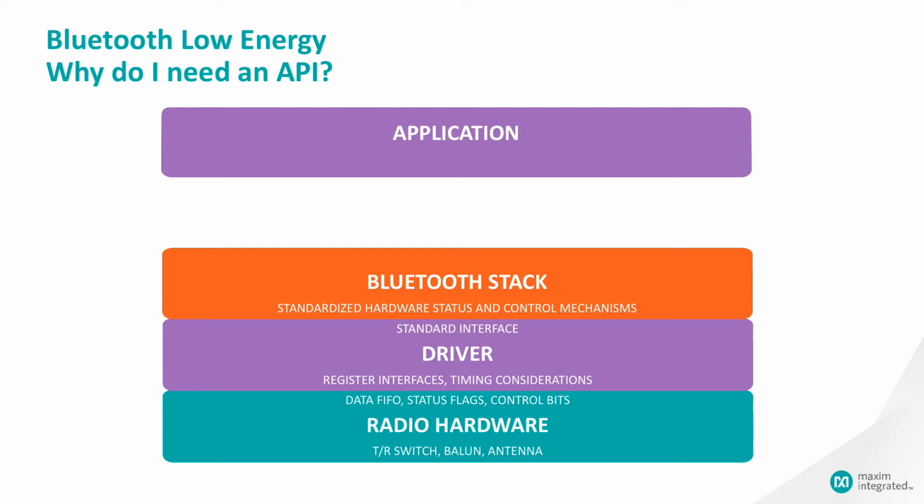So, the application talks to the Bluetooth stack, right? Well, not so fast. The stack itself exposes a lot of low-level concepts that the application really doesn't care much about. What you really want to expose to the application is more the concept of a channel or a port. You just dump data in and suck data out, rather than thinking about exactly what the source or destination of the data actually is.